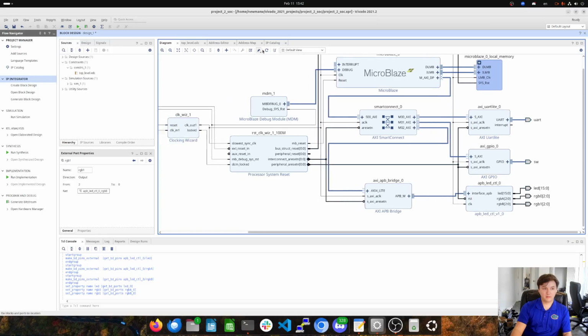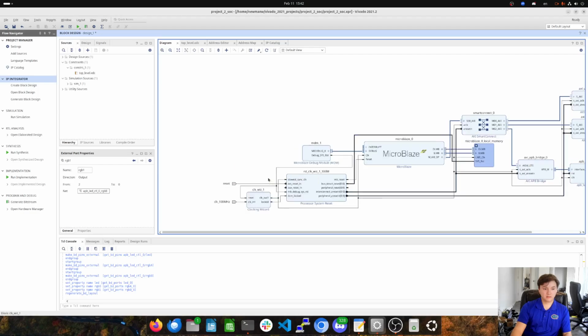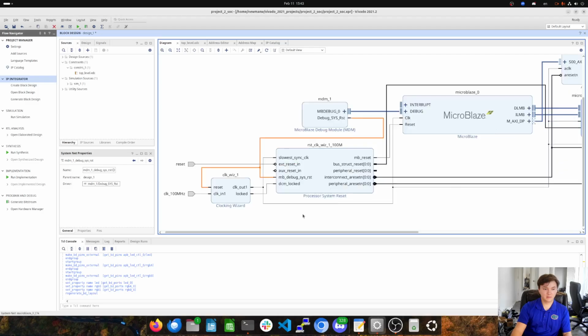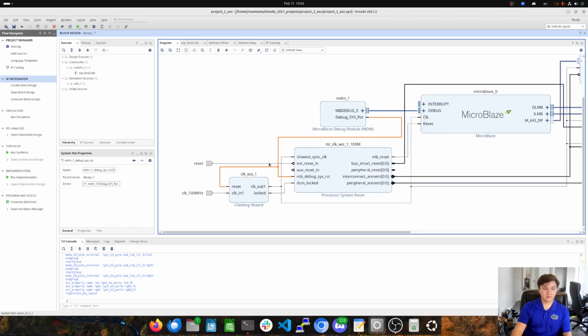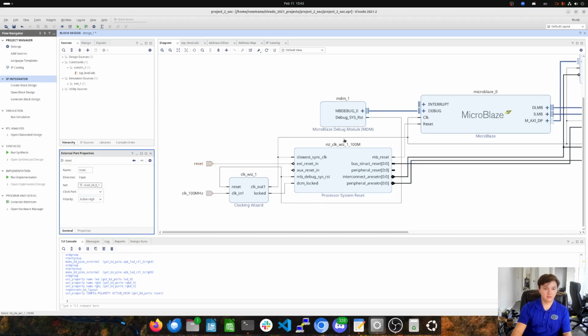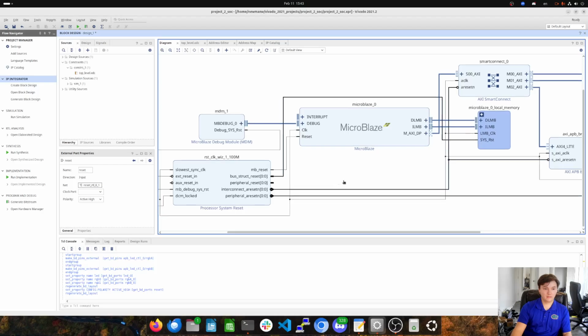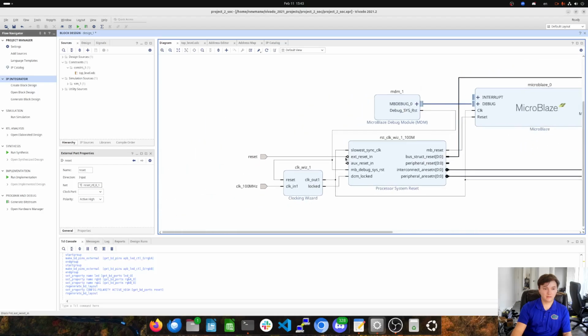And I'll reload everything. And so I guess one thing to consider is whether the reset of our button is active low or active high. So we need to change the reset pin on our device. So we have to say active high pin, and let's reload everything. And now that that's active high, this is expecting a reset in of low. So it's expecting an active low pin.